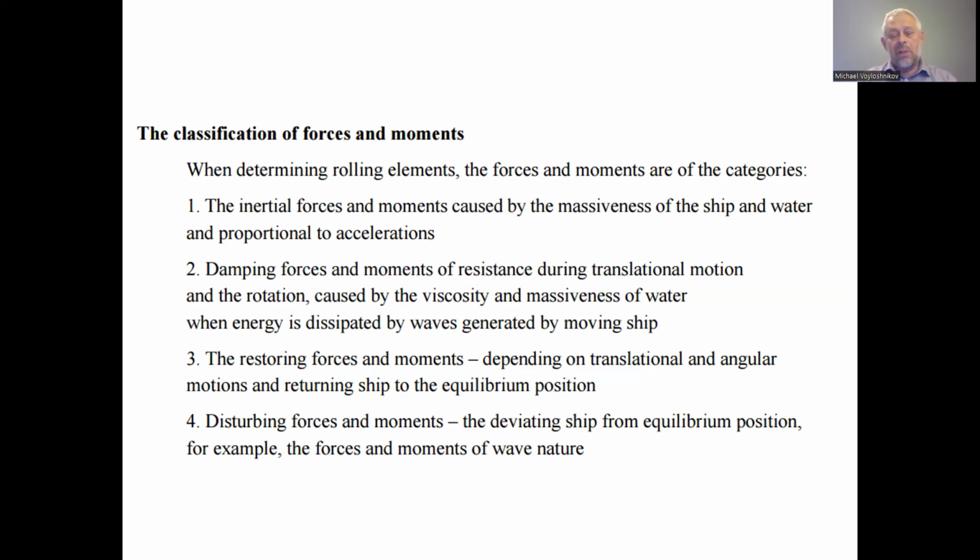The second category is the damping forces and moments of resistance during translational motion and rotation, caused by the viscosity and massiveness of water. The cause as the massiveness of water means that the energy is dissipated by waves generated by the moving ship. And the third category, the restoring forces and moments depending on translational and angular motions and returning the ship to the equilibrium position. This is not for all kinds of the ship motion.